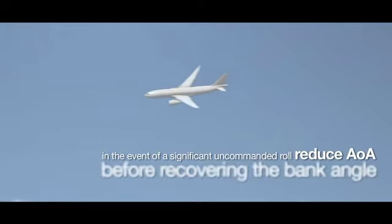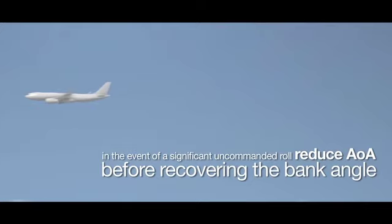In the event of a significant uncommanded roll at the stall, reduce angle of attack before recovering the bank angle.